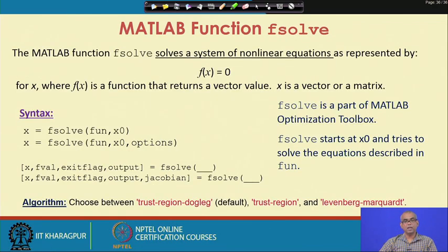Now, next let us take another example. This time, the use of fsolve. The MATLAB function fsolve solves a system of nonlinear equations as represented by f(x) equal to 0. So, basically fsolve solves a system of nonlinear equations. It will find the x vector for which f of x equals 0. fsolve is a part of the MATLAB optimization toolbox.